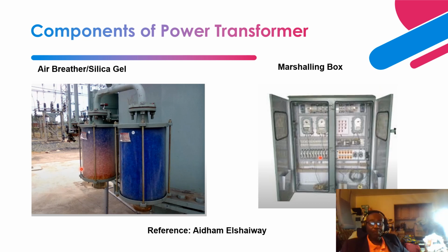Inside this marshalling box are also heaters, right? These heaters are the ones that keep the moisture away from the marshalling box, because you don't want condensation on the terminal blocks of the marshalling box.